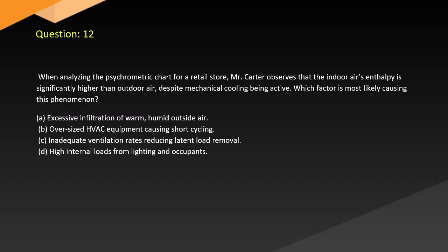Question 12. When analyzing the psychrometric chart for a retail store, Staccato observes that the indoor air's enthalpy is significantly higher than outdoor air, despite mechanical cooling being active. Which factor is most likely causing this phenomenon? A. Excessive infiltration of warm, humid, outside air. B. Oversized HVAC equipment causing short cycling. C. Inadequate ventilation rates reducing latent load removal. D. High internal loads from lighting and occupants.